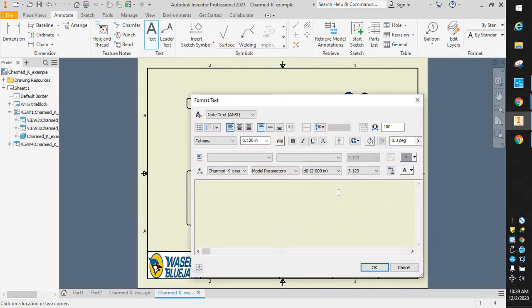I'll just click on that. It gives me a little properties box here, and you can actually pull this right from the My PLTW as far as what you need. But what you need is notes. You need to have all dimensions in inches. You'll have to have material, and that is PLA plastic, and you have to have the density.